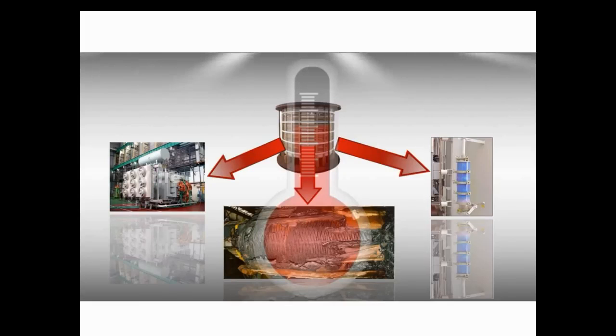If we take all these factors together and add in heat as a control factor of the insulating system, we discover oxygen in the cellulose. Then we get what we call chemical degradation, which is a breakdown of paper. It means that we gain acids, peroxide, more oxygen, and thus more moisture again. It results in degradation of mechanical strength, as well as dielectric degradation, that is, dielectric properties loss. And this is the result.